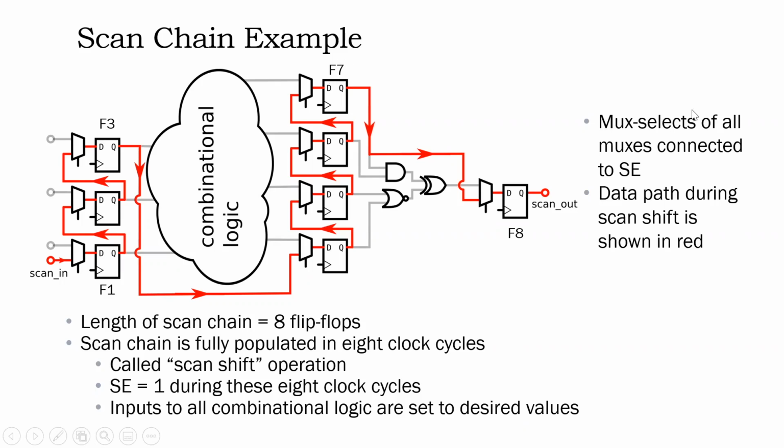So obviously in a real scan chain, in a real netlist, the flip-flops in the scan chain will not have this very regular instance name. They'll all be random and arbitrary instance names, but just for the purposes of our understanding, let's say that these instance names also reflect their sequence in the scan chain. Again, that will never be the case in real life, but just now I'm naming them like that.